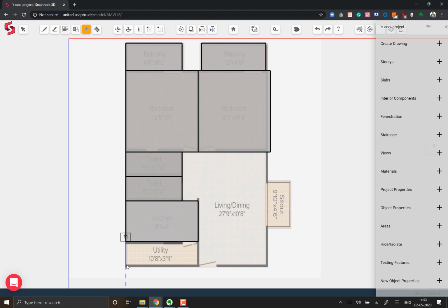I will draw 1100 mm over here, and along this direction, I would have to draw 4500, and by mistake, say I added an extra zero, it will create a very long line. And now it's a mess. So to be able to come out of it, if I just press the escape key, you will see that this line will disappear and I can still have control over drawing it again. Now I will type 4500 again as my correct value and can continue drawing. I'll double click here to complete it.